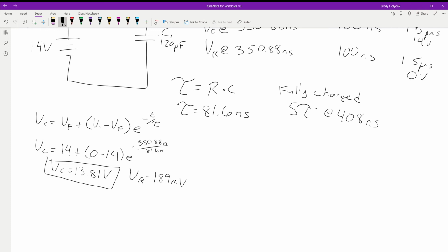Depending on the frequencies you run, I can't remember exactly what these guys operate at, but one of the things that they put out is a waveform of a frequency. And you start approaching that thing, these things raise hell with them. So one of the things too is if you're starting to realize your readings are wrong, lean over top your board when you do your measurements. Your body will block those signals from getting into your circuit.